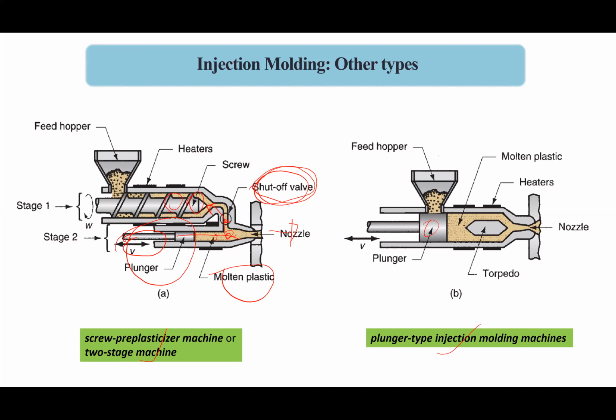First the material comes into the location, and then you use the plunger to push it in here, and when the plastic gets melted, you push the material into the cavity. After that, when the plunger is moved backward, another stock of material comes in here, and you push it up to this point, and then wait for some time to get it melted, and when the melting is complete, you push again.